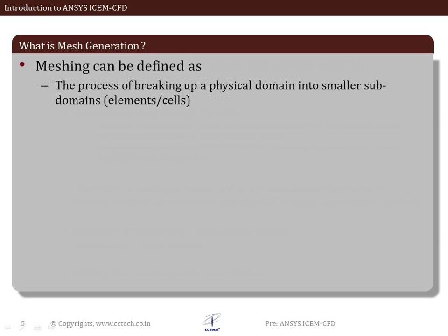In the overall CFD cycle, mesh generation is the most critical and many times a time-consuming process. The simplest definition of mesh or grid generation is that it is the process of dividing the domain into small subdomains. You can imagine that the smaller subdomain is equivalent to a control volume we have used during the derivation of fluid dynamics and heat transfer equations. These small subdomains or volumes are typically referred to as cells or elements in the CFD community.